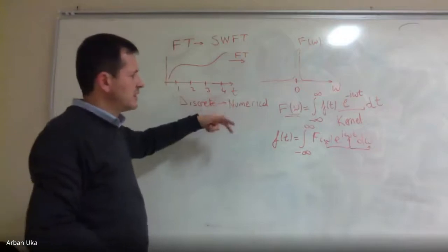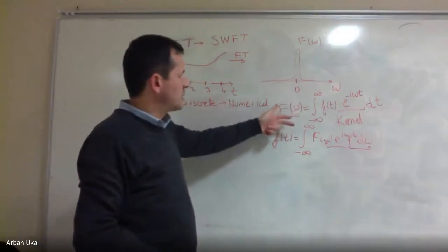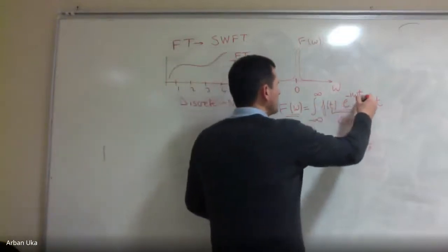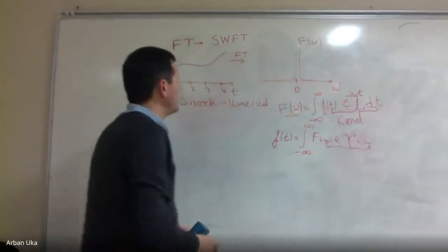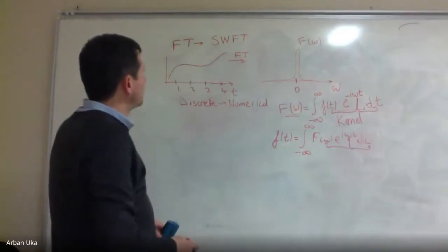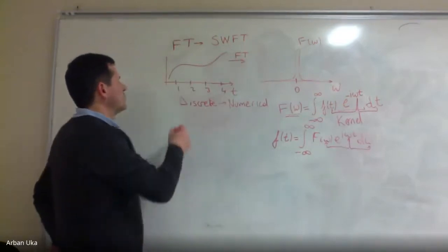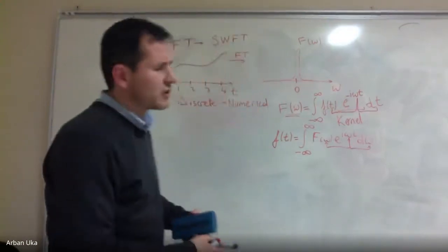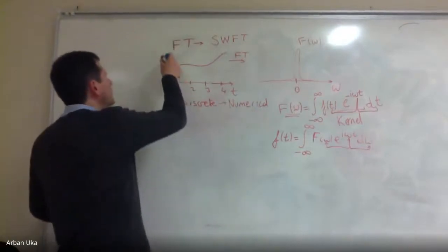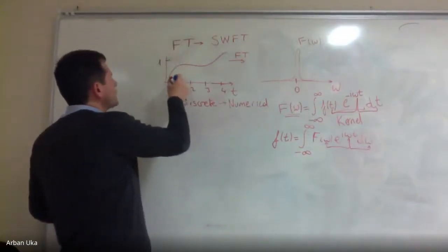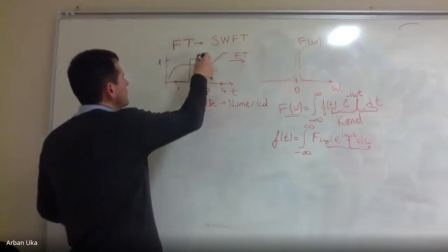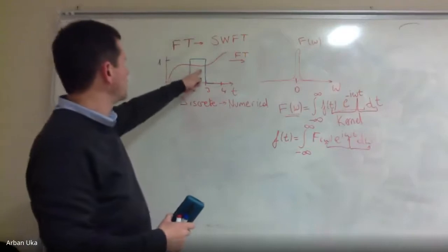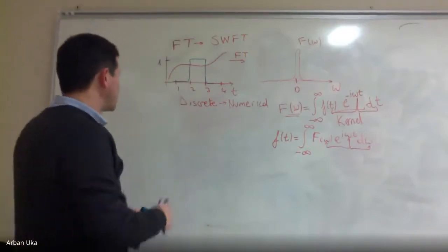Okay? But it's good to remind ourselves of how this is, and also to understand that really, once we integrate, all of these terms will get lost, these time functions. And now, what Gabor developed, he said that when you take the Fourier transform, we can multiply the given function with a window, which is going to be 0 to 1. So we can multiply it like this, 0 to 1, and take the Fourier transform of only this component. Then what happens is the following.